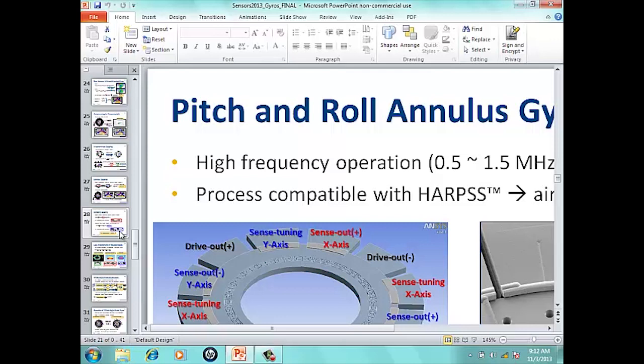which is basically due to these differences in the quality factor. The effects that I described are related to having a signal that comes exactly at the same phase as the array, so you can't really distinguish one from the other. So that's why it's critical to have equal Qs. Now, this is more important in whole angle mode gyros, where you have this continuous energy transfer between the two modes. In rotation rate gyroscopes, since you're always replenishing the energy loss for the drive mode, the effects of Q differences might not be as critical.